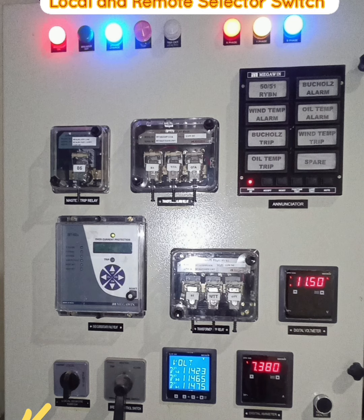An electrical local and remote selection switch is a device that is used to switch between local and remote control modes of an electrical system. It is typically used in industrial and commercial settings where a system needs to be controlled both locally and from a remote location. In local mode, the control of the system is performed directly at the site where the system is located. For example, if the system is a motor, the operator may use a local control panel to start, stop, and adjust the speed of the motor.